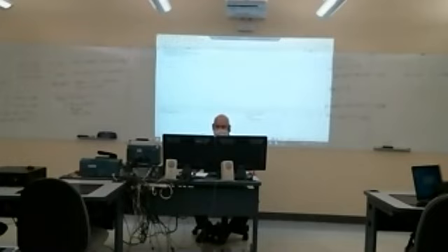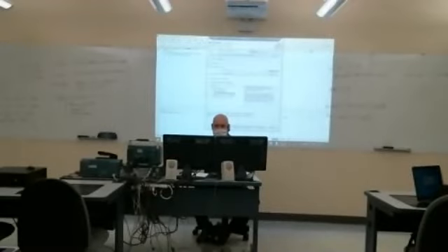Now, typically what I want us to do in the homework for this first exercise is say new and then CCS project, Code Composer Studio project.